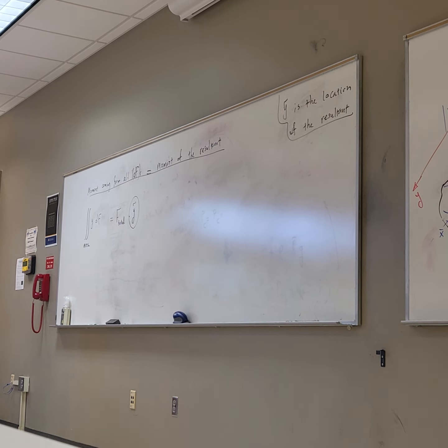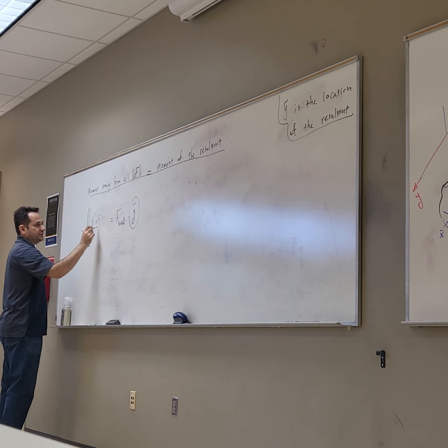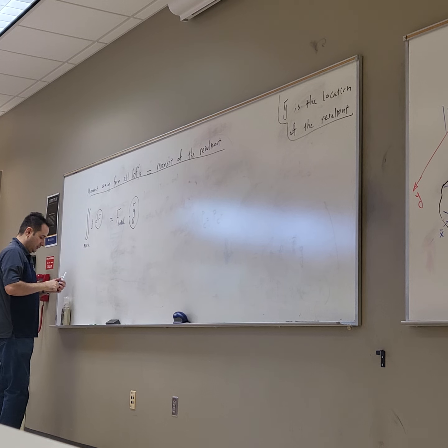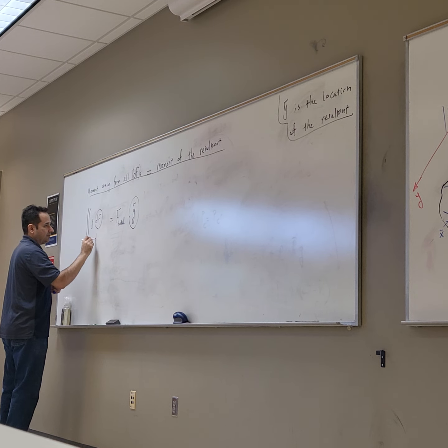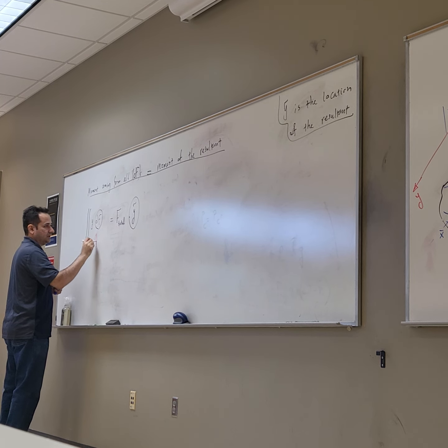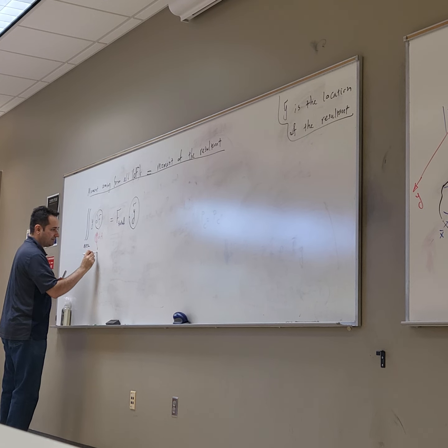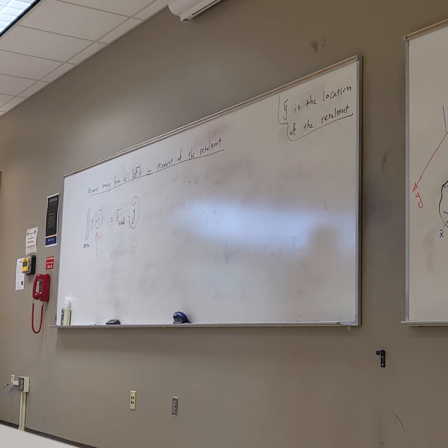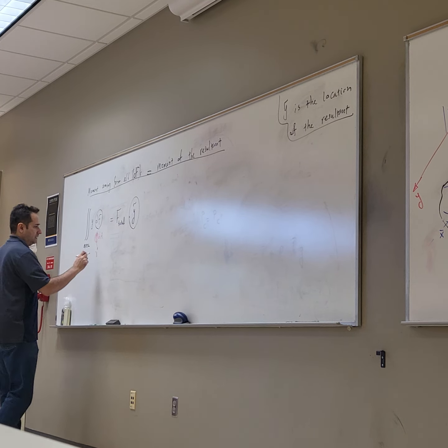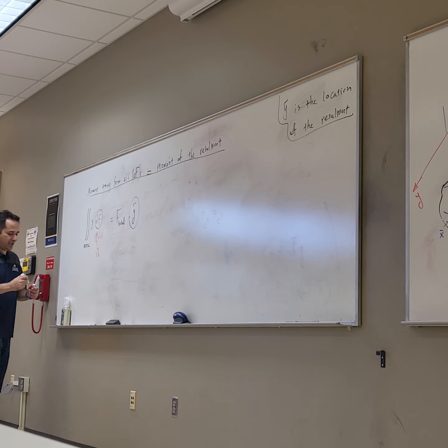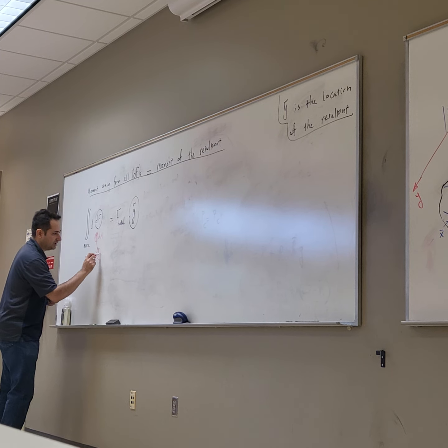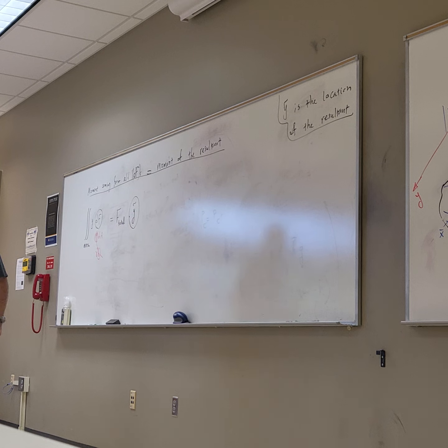Now that's what I'm trying to find, the location of the net force. So let's go ahead and expand df, just like I had before. I first write p dA, and then for p, put gamma h, so gamma h dA, and h was what? y sine theta.